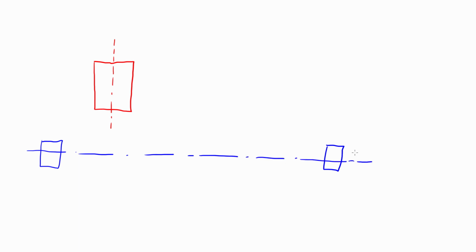And they form an axis as well. Then with the first kind of rudimentary geometrical tolerancing, we could put a tolerance like this, where we say we want perpendicularity within a certain amount, let's say diameter 0.1, and we want this axis to be perpendicular down to this axis.